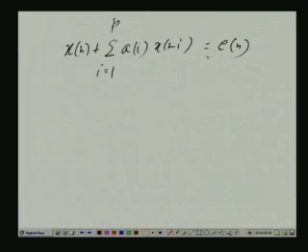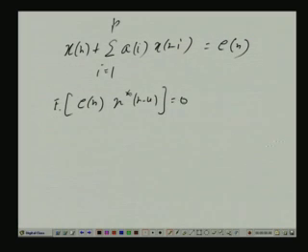Okay. Now, there we discussed how to find these equations. We know this orthogonality, this is what we did yesterday, and then I made a small mistake, so I am redoing this step. E of E n x star n minus k is equal to 0 for k equal to 1 to p. These are the orthogonality conditions. If you now substitute the left hand side for E n here and do the multiplication, you can verify easily, we start with k equal to 1, then go to k equal to 2, and then k equal to p progressively.